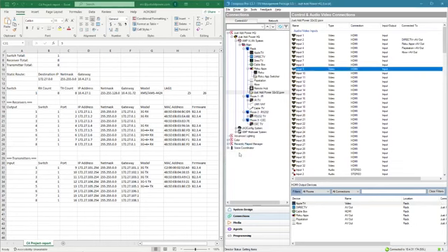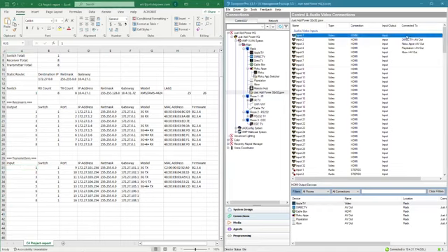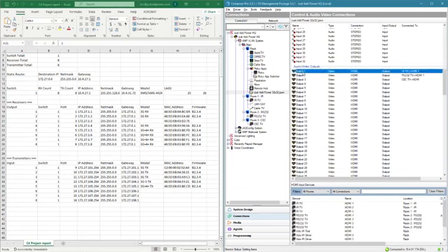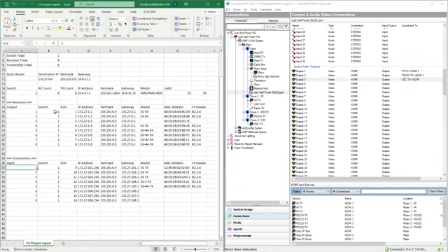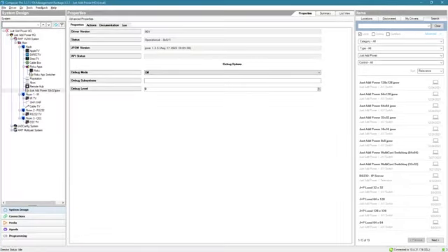But because we don't know what port the devices are going to be on before we build the system, we always go by the input number when matching to Control4. So because it's the device labeled as input 1 or transmitter 1 in Composer, it is input 1 as well. And the same thing for the outputs. The outputs are 1, 2, and 3, which luckily for us in this system are actually ports 1, 2, and 3, so it matches. Those are the 2 most common mistakes we see in Composer systems.